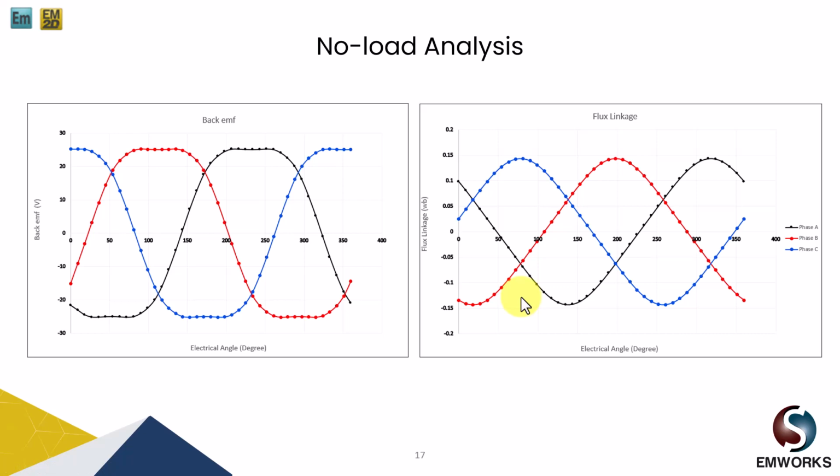There is not much difference between the surface mounted PMSM and the Halbach array if we use a ratio of 0.8. Still, the majority portion of the pole arc is dominated by a radial flux magnet, and we get a flat top at the back EMF waveform. And also, this is not close to a sinusoidal waveform and contains a lot of harmonics. For the Halbach array arrangement PM motor with 0.8, we get a good flux linkage, and it's due to its concentrated winding arrangement.